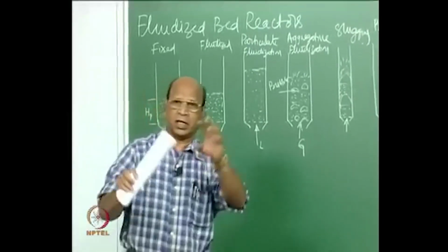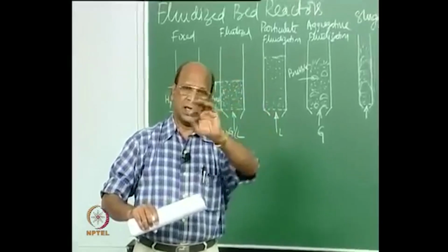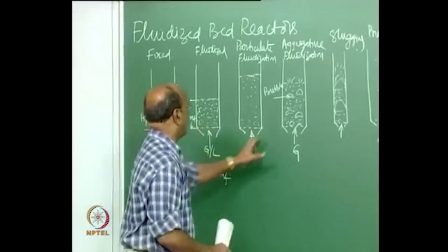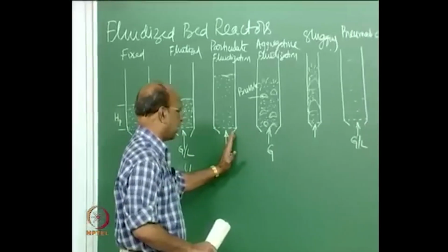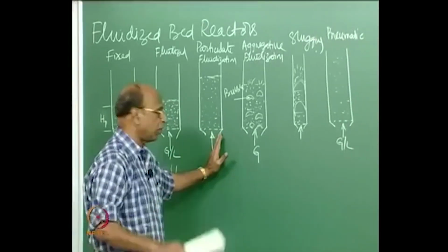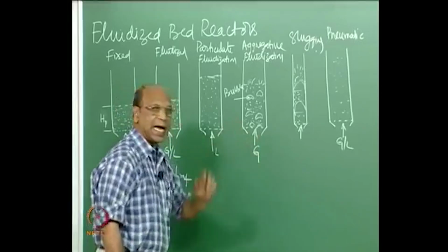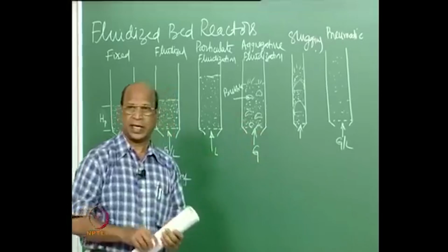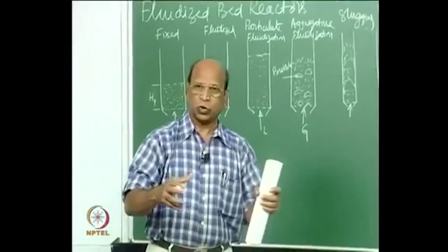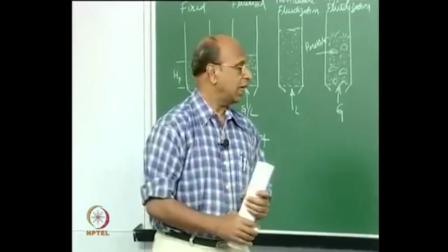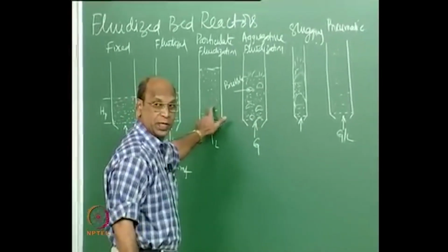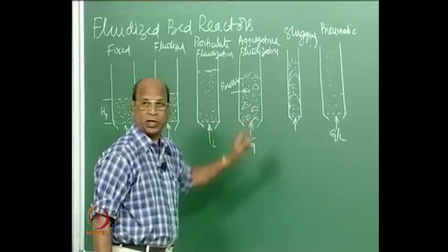Nicely expands means anywhere smooth fluidization, and the interparticle distance is uniform throughout the bed, etc. And if you take the same condition, that means 2.5 UMF or 3 UMF, and then conduct the same thing with gas, right, the gas will have aggregative fluidization, where the gas goes in the form of bubbles. So, that creates aggregations, and that also creates good mixing. In fact, you will not have that kind of good mixing here. You will have here very good mixing for solids.